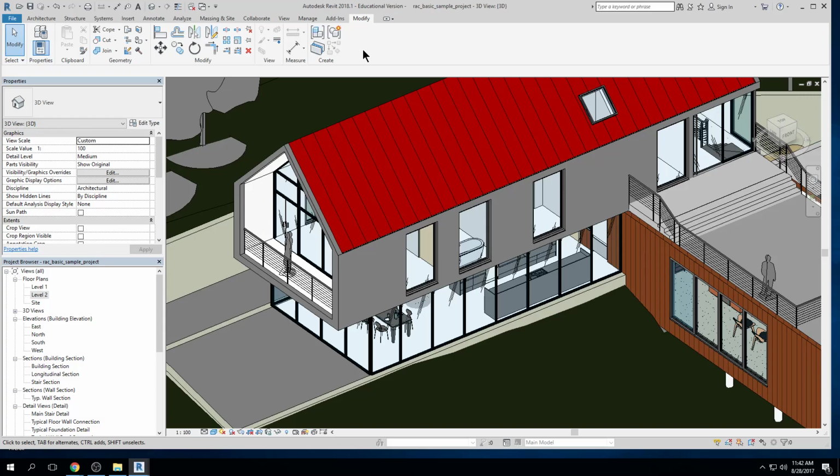Let's say we establish some weird relationship like that, right? You could go back in and break that pretty easily. But in relationships where this wall comes in and meets that wall, and if I move this wall right here, that wall moves with it, that's kind of inherent, and other things won't work if you break that parametric relationship. So yes and no, I guess.